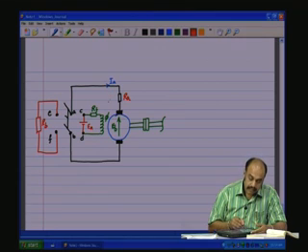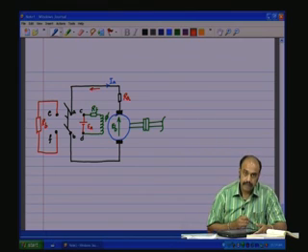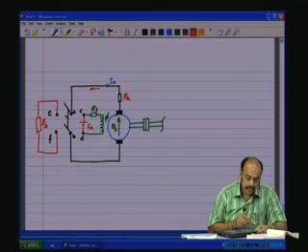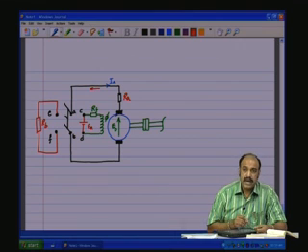So, a current is going to flow in the reverse direction, or if the current is already flowing in IA, that is going to decay pretty rapidly, because it gets dissipated in RB as IA square RB.